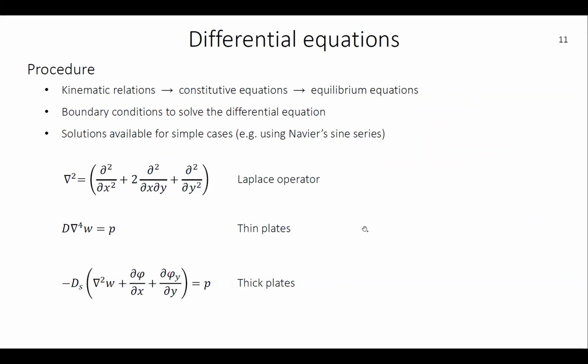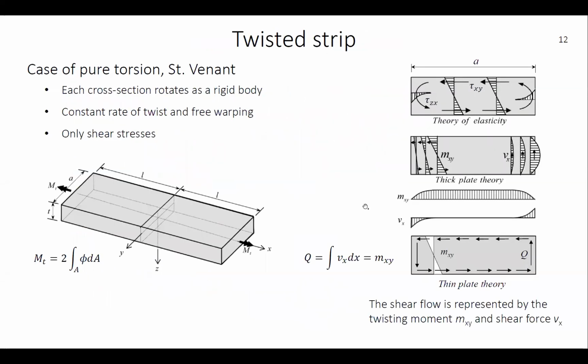So those are the differential equations, but they are quite lengthy and difficult to solve in the general case. So then we would like to use finite elements to solve it. But before we go into that, another interesting distinction between the thin and thick plate theory, which is also important in the finite element context, is if we study a section of pure twisting.